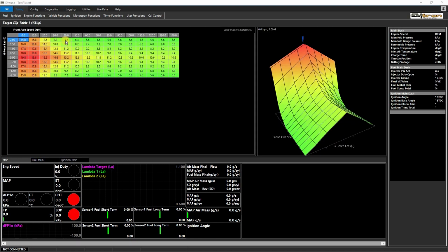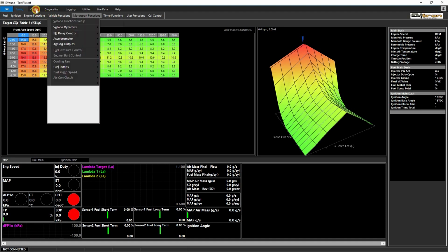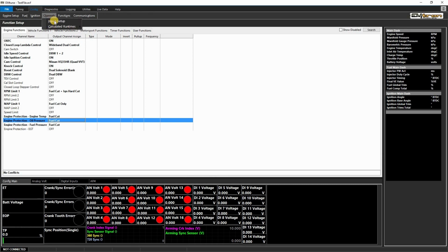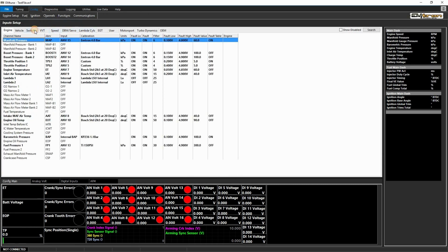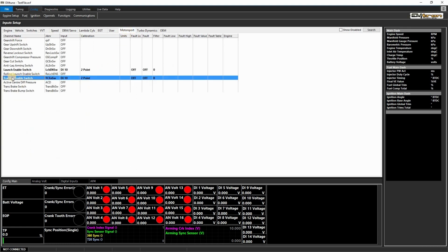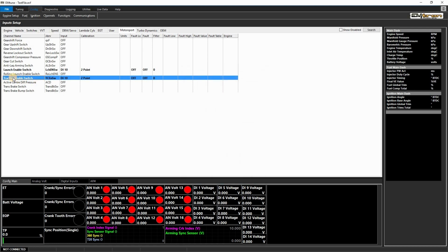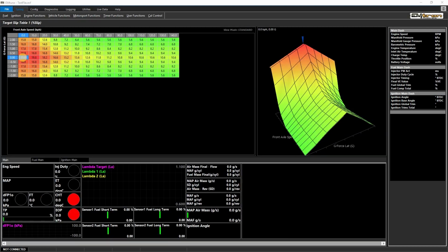Some advanced ECU functions have switch inputs that can be assigned to turn them on and off. This way, the function is enabled and can be fully configured, but its state of operation is controlled with these input switches. Functions that have enabling switches under inputs are always on if the input is not configured. For example, if you enable motorsport traction control, but do not have a traction enable switch configured, the traction control will always be on. Inputs can also be copied and used in multiple places.